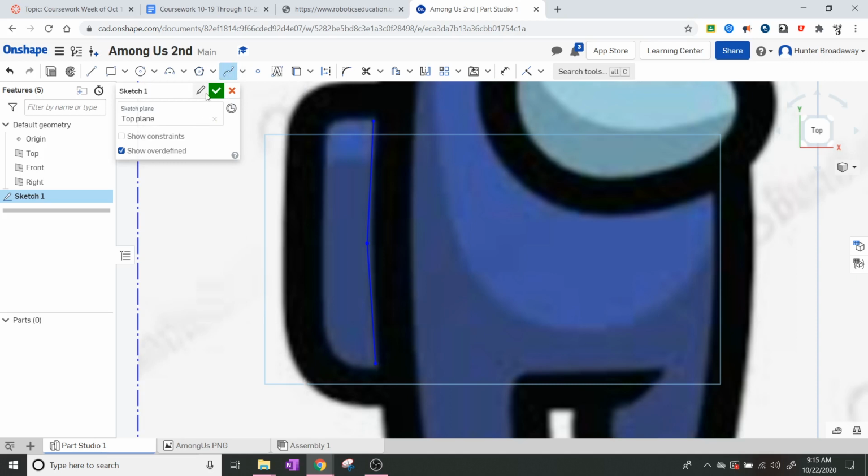Okay, so if you get down to that bottom part, into the blue line, click on the dot that we made before, and then you're going to click on the spline button, and you're going to have to kind of experiment with this. You may have to undo it a couple of times because you click, you move the mouse over, and when you click again, it's going to make a curve. The clicking should move out to some kind of curve part. So I'm going to just make 3 dots.